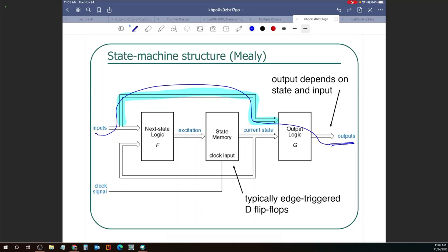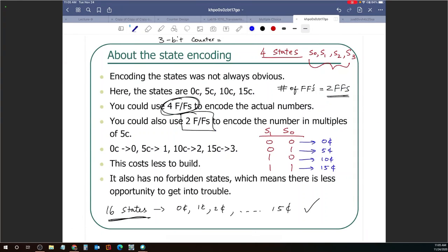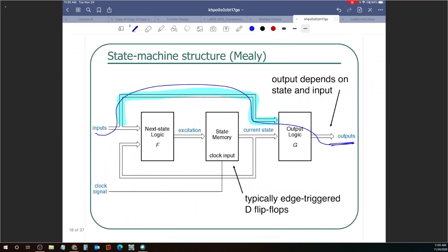Moore needs to wait for the clock to change output. The Moore machine outputs can change only after there is a change in the state, which means it is dependent on when the state changes. And we know that flip-flops can have a change of state only after the active edge of the clock. So the outputs for Moore can only change based on the clock. Hence, they are called synchronous with respect to clock.